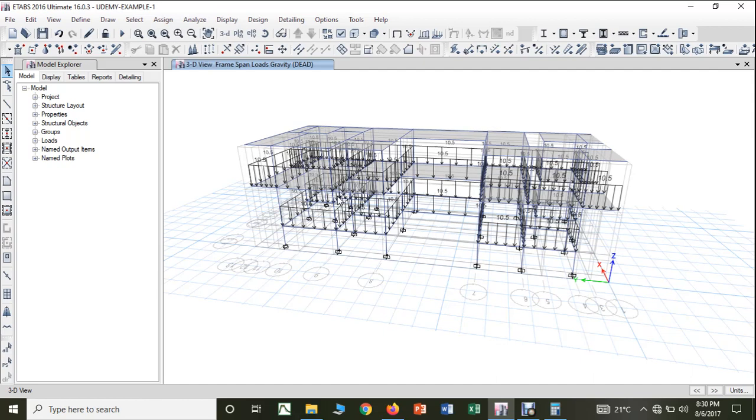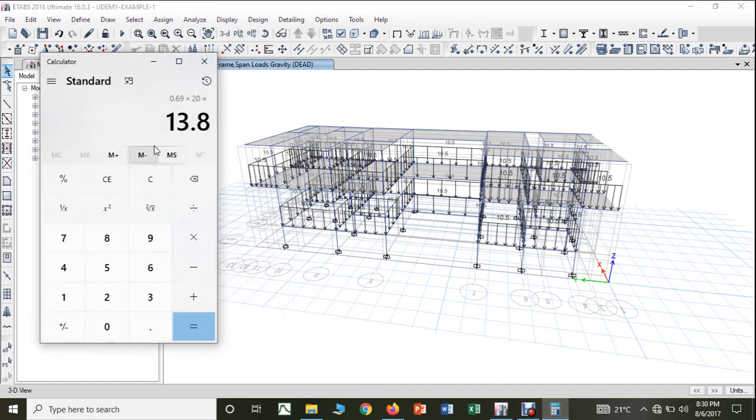Okay, yes. So now when it comes to your top floor, that is when it comes to your parapet wall, there when I convert that, you can see the thickness will be maintained, 230 by 1000, no change, multiplied by, instead of applying the 3 feet, let us apply 1.5 feet.